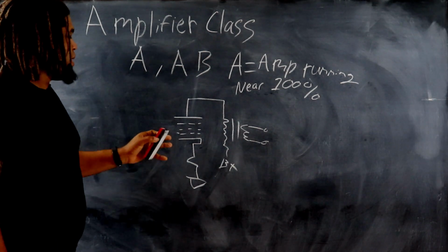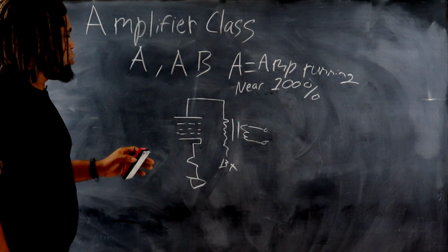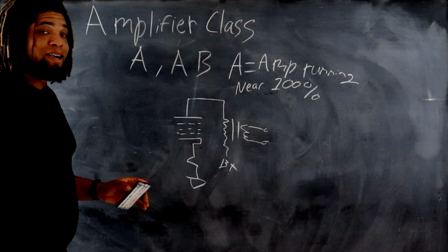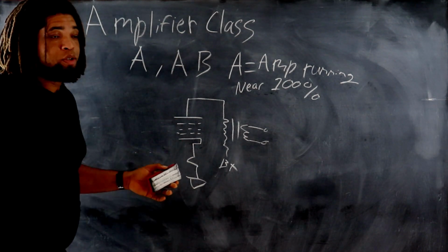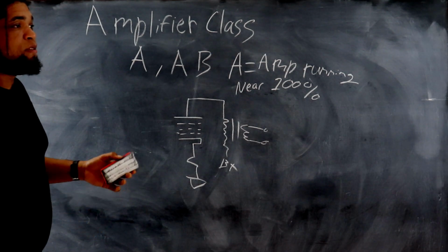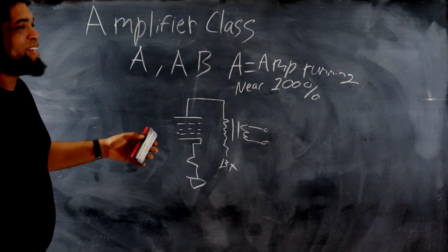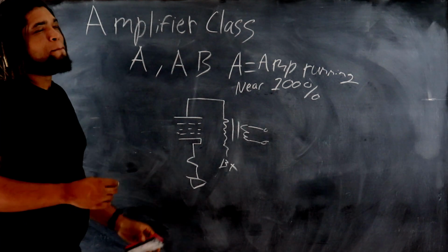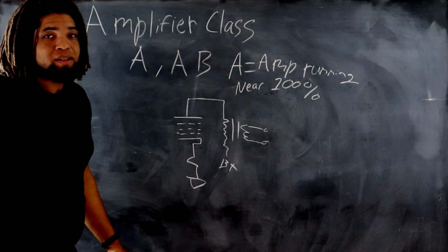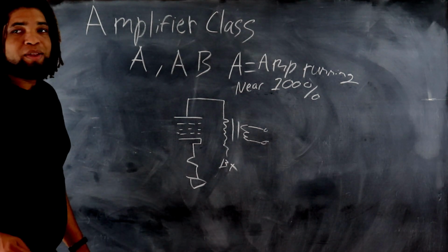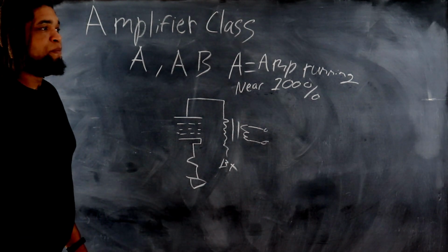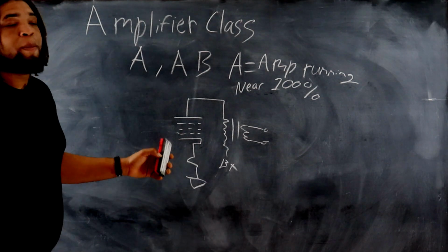One of the other limitations that you could find in the tube world for a Class A amplifier is that you're limited with wattage to a certain degree, and it becomes even more inefficient as you're trying to get any wattages, let's say above 20 watts, 30 watts. You could push something like a KT88 maybe to 30 watts using one tube, or else you'll parallel the tubes.